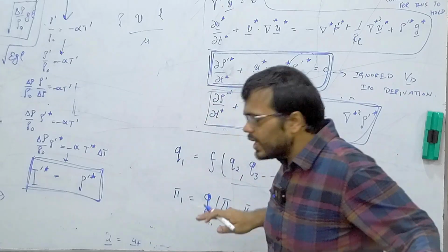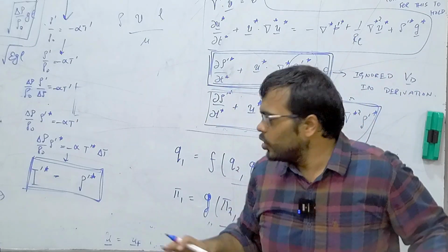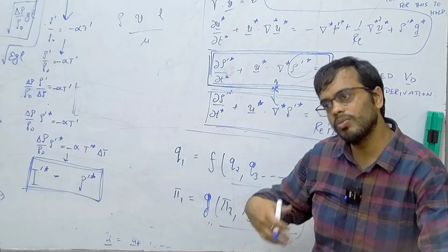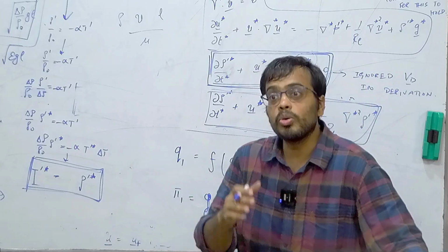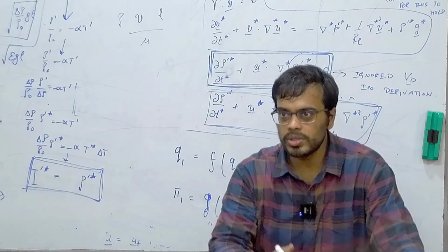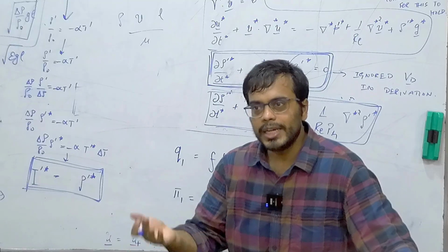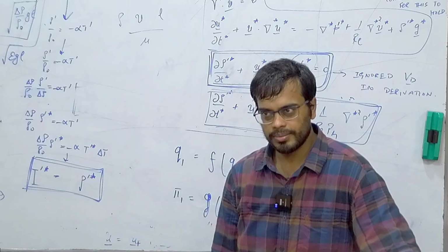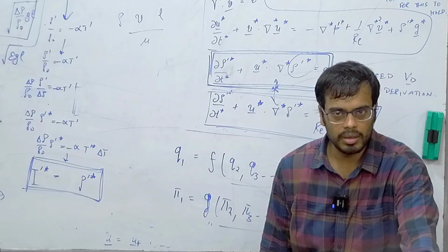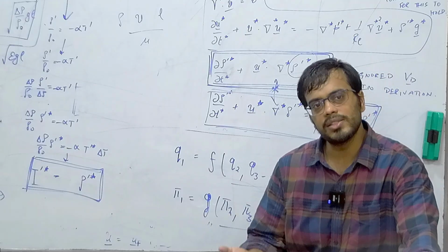What dimensional analysis is trying to say is that you will get the same pi 1, whatever group you have formulated on the left hand side, you will get the same value of pi 1. So, experimentally there may be different setups that you have used, but physically it is the same data point. That is what this pi grouping is trying to tell us. Physically it is the same data point.